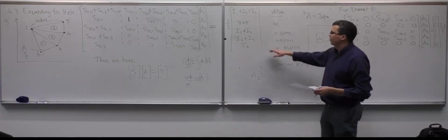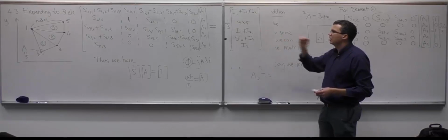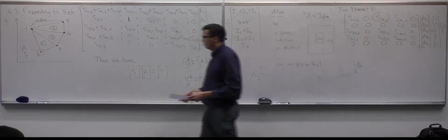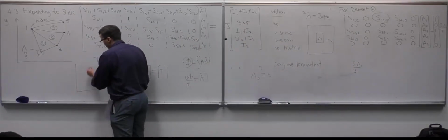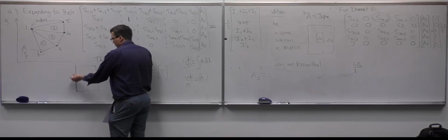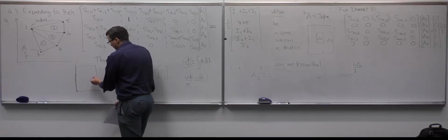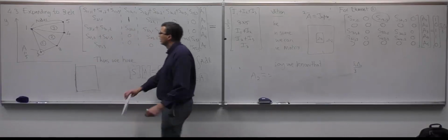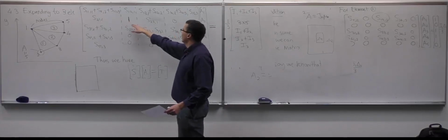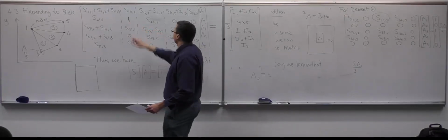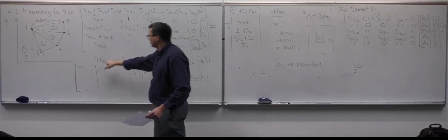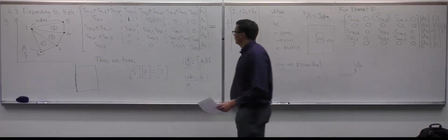The boundary condition is relatively simple. You just have to know that if you have a problem where the boundaries are known on the edges, then you need to keep track of the values at the node points on the edges. Once you've formulated your problem, you can go back and put in the ones where the vector potential values should be set, and then on the right side you put in the value that you want.